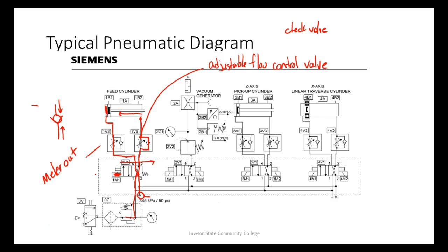Well, if we metered in, this guy would come up here and push, the air would move, the air would uncompress because it's not pushing against anything, right? Then the air would compress, then it would move and the air would compress. So what we're doing with this meter out is we're constantly putting back pressure into the exhaust. So we're not letting the exhaust flow out real fast. What it means is this pressure is always pushing against something.